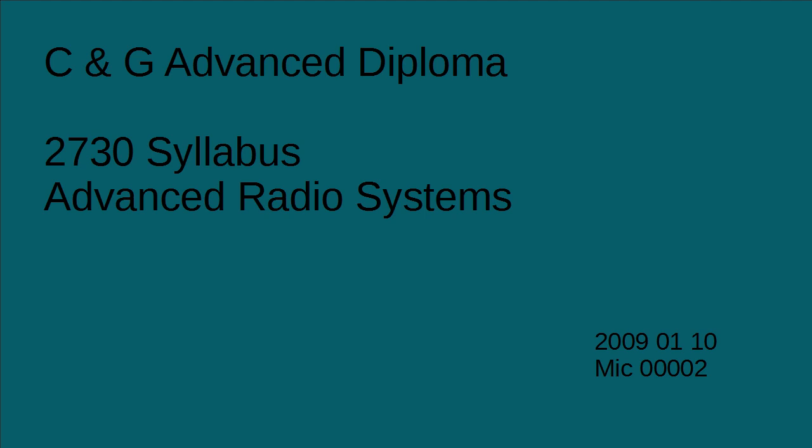Second point, let us say L is the length. Here we use L physical, the physical length of the antenna. Instead of that, on this side you have A physical, which is called the physical aperture of the antenna. What is the difference? This is in meter. This is in meter square. This is an area. This is the length. There is a physical length on this side, there is a physical aperture on the other side.